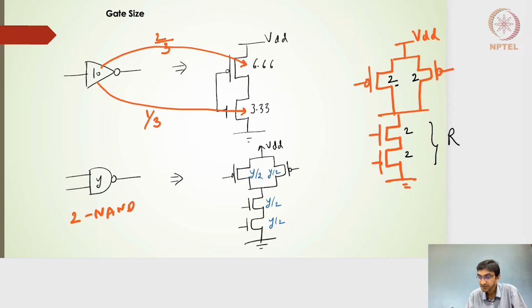So here, on the input side, if I pick up this being my transistor A, or the input A, which goes to this particular transistor and then this particular transistor. So the input size of the two input NAND gate is nothing but 4, where 2 parts are going to the PMOS and 2 parts are allocated to the NMOS, equal parts. So if I have a size of Y here, total should be Y here.